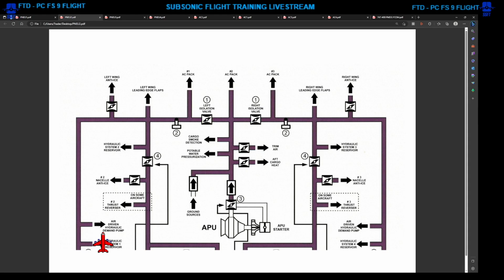In the 747 Classic, they were all air-driven demand pumps, but in the 400 and the Dash 8, they went to supplying electric demand pumps for systems 2 and 3, which helped reduce weight, basically. Pneumatics is also supplied to the left wing anti-ice system and the right wing anti-ice system. The wing anti-ice valves would open either automatically, or we can open them manually if you have the manual switches, and that would allow bleed air to flow into the leading edge devices to supply wing anti-ice.